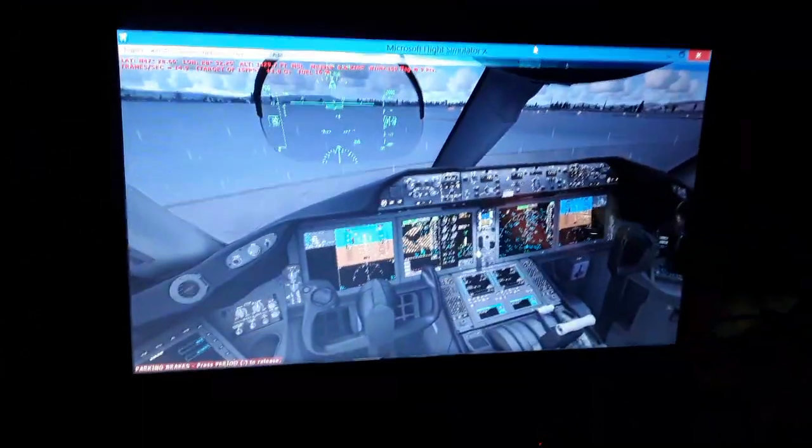The ILS localizer protocol is going to use flaps of like 25-30 degrees for approach and landing, and an airspeed of like 150, 160 or 170 knots, and also a pitch attitude of 9 degrees for approach and landing with the landing gear extended. You're also going to see a pitch attitude of 9 degrees for takeoff. I forgot to mention that, 9 degrees or less.